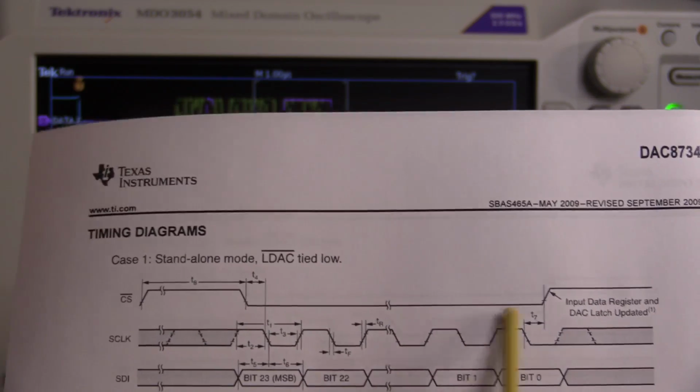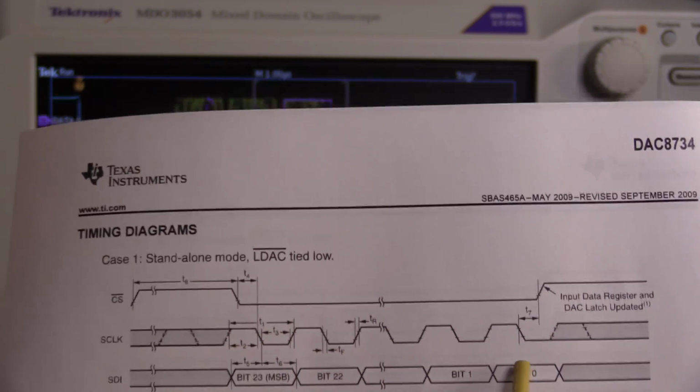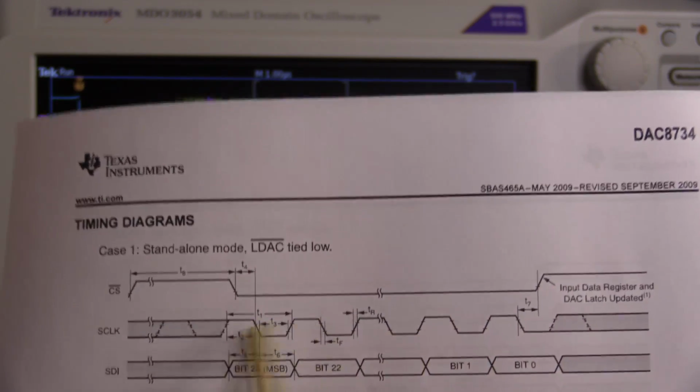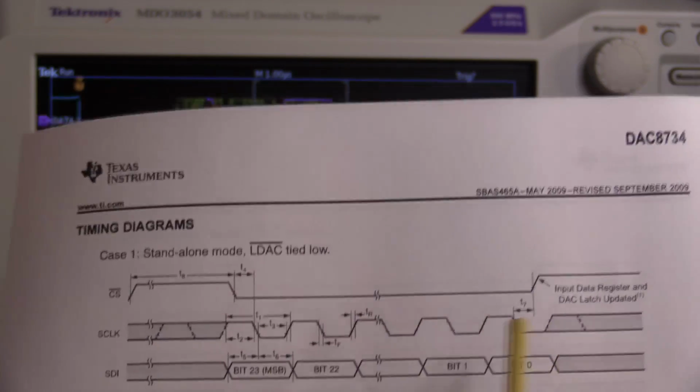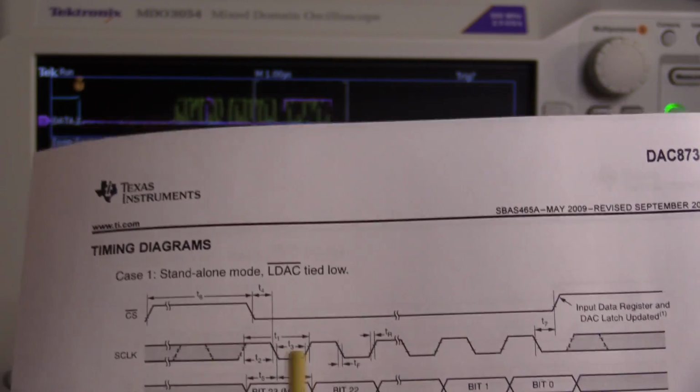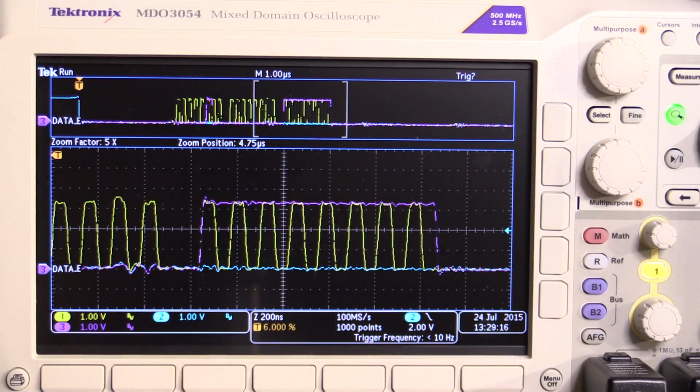So each time it's happening in the middle, and that's what clued me into the fact that this was happening incorrectly. Now what I'm going to do is change the software to use mode 0 again, and we'll have another look. I'm just trying to remember what the actual code is for 10101010 on the data. We'll see if we can put that in a moment, and we'll see with the actual data signal what the differences are. But for now I'm just going to change this to mode 0, and we'll do exactly the same screen capture, and you can see the difference.